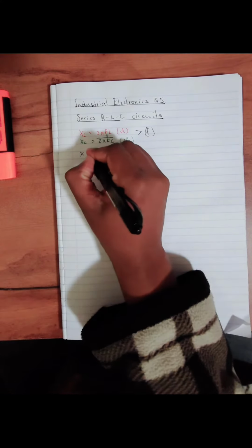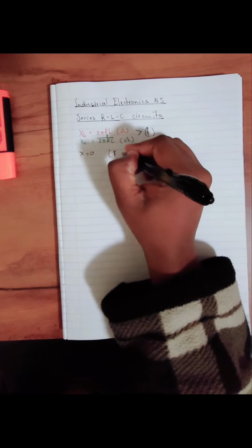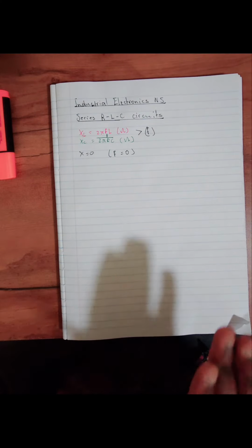In a DC circuit, guys, the reactance is equal to 0 because the frequency of a DC supply is 0. A DC gives you a constant value of current and voltage. It doesn't fluctuate, so we don't experience reactance when we're talking of a DC circuit. The only form of opposition to current flow that we experience is resistance alone.